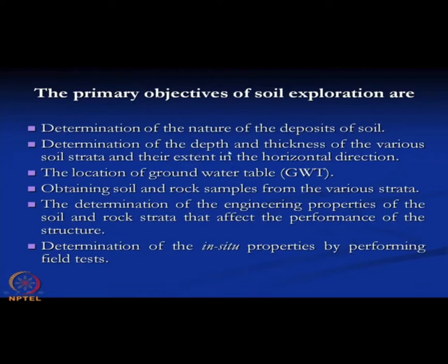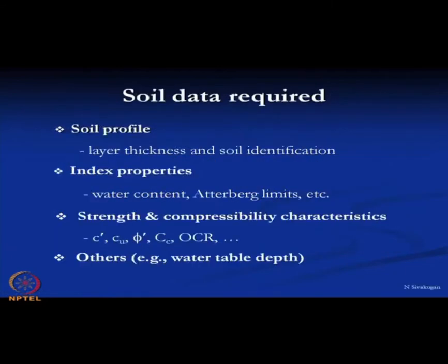What is the depth and what is the thickness of the various soil strata is very important for any foundation design. Then the location of the groundwater table, because the groundwater table also plays a very important role. Then obtaining soil and rock samples from various strata, the determination of the engineering properties of the soil and rock strata that affect the performance of the structure, and determination of the in situ properties by performing field tests. So, these are the objectives of soil exploration.